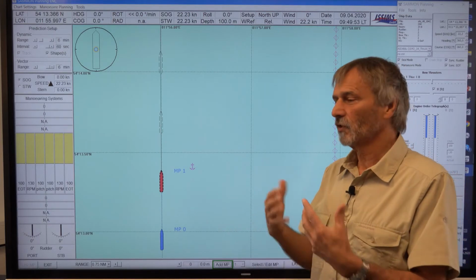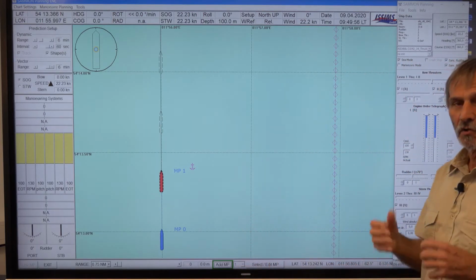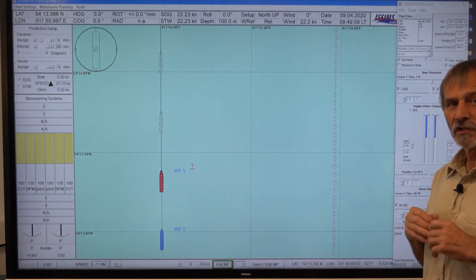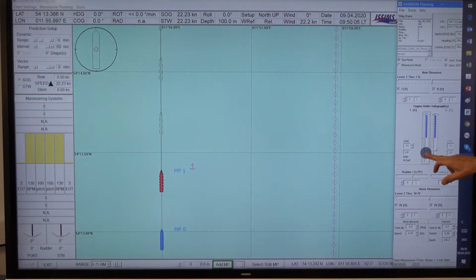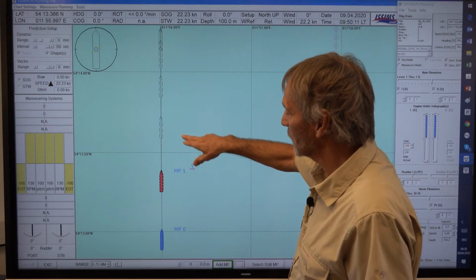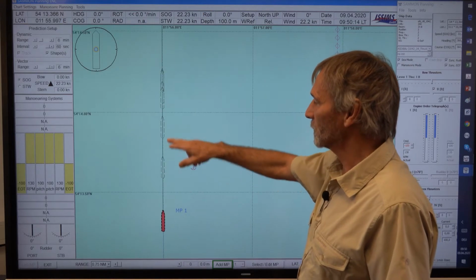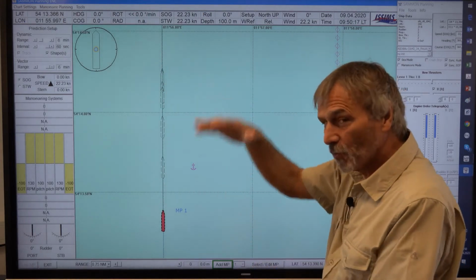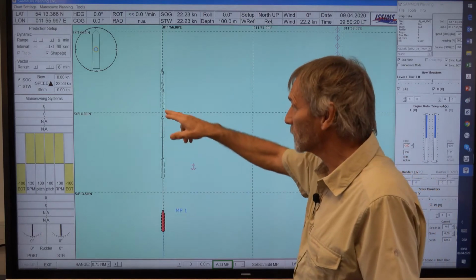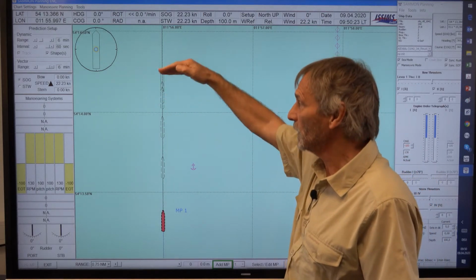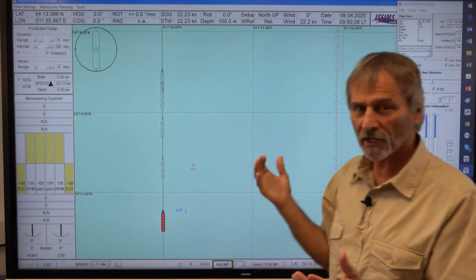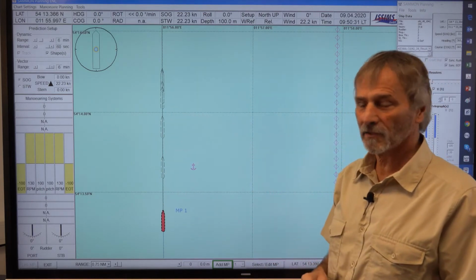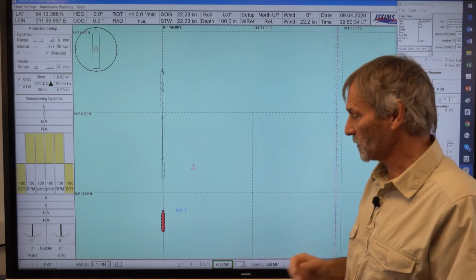And here we can do the next maneuver, for instance, to reverse the engine as a crash stop. For this reason, we take the engine order and reverse it until minus 100%, full astern. What you immediately have seen is the shapes here, they have squeezed together because the ship is getting slower and slower. And here is the final reach the ship has had. And then if you enlarge the prediction up to 24 minutes, then it pulls back. But we want to measure how long the stopping distance is.